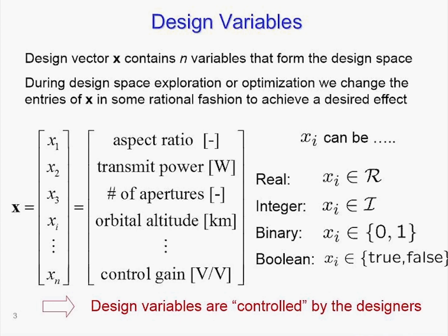Yep. So weight often shows up as an objective. Max takeoff weight is often used as a surrogate for cost and fuel burn and everything kind of rolled up. Cost might be another one. Operating cost, or it might be entire life cycle cost. Could be environmental impact, could be noise. All different kinds of things.